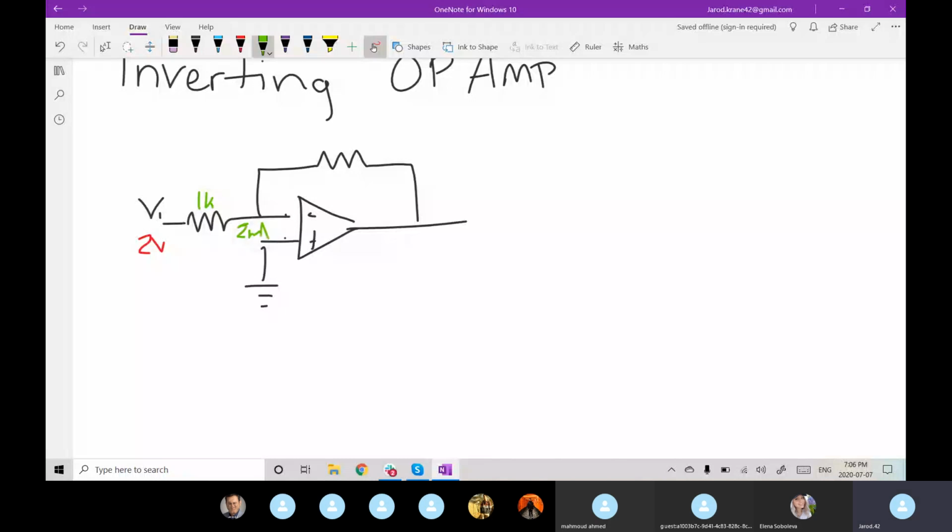There theoretically should be. But if we were to probe this pin, we would get nothing. We get 0 volts because we have forced our non-inverting to ground. That is hard set 0 volts. We can't influence this one.